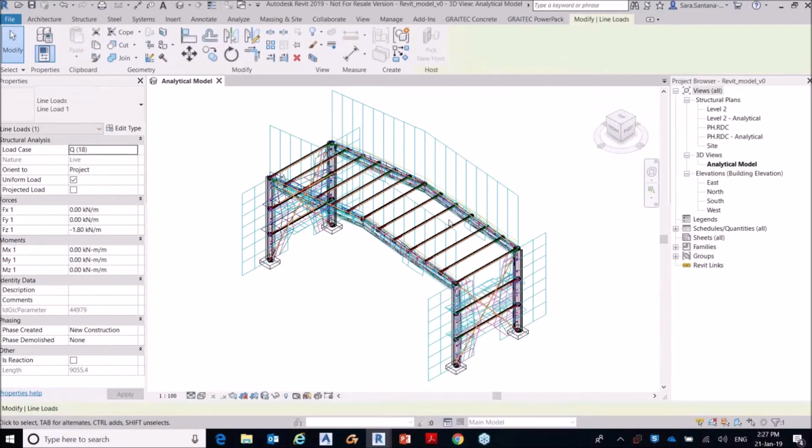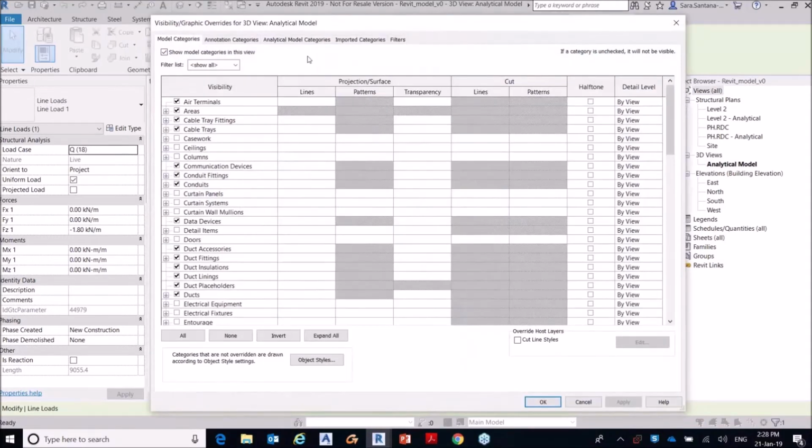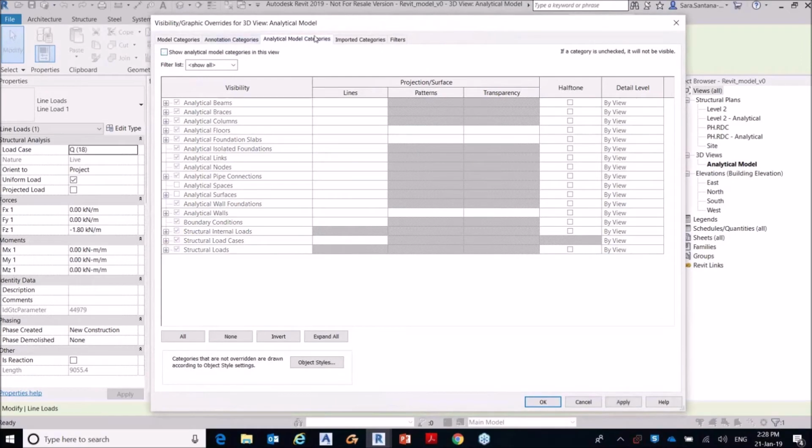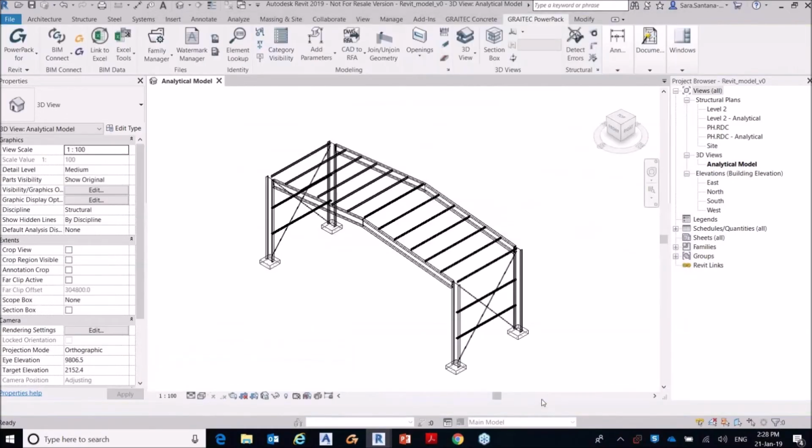So that was a lot of information, of course, in Advanced Design and how you can analyze your model in an efficient way and save a lot of time in that regard. Here, one thing to point out: of course, you might not want to see all these additional elements. These are Revit elements, inside of Revit, these load cases here. If you just wanted to turn them off, all those visual settings can be controlled here. So if we were to turn everything off with the analytical model, you'll see that all those elements will not show.